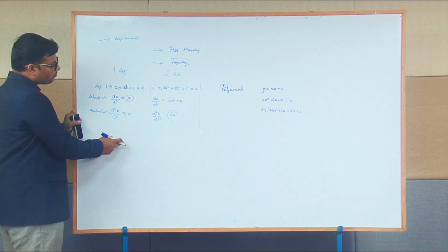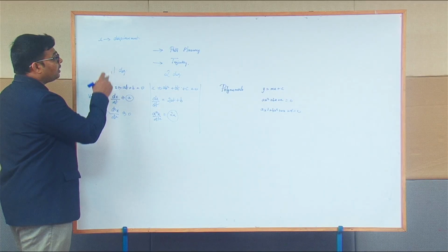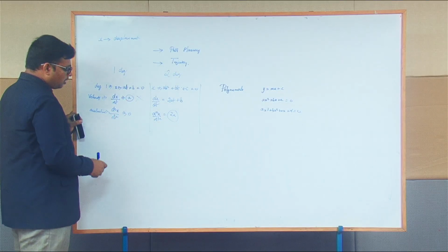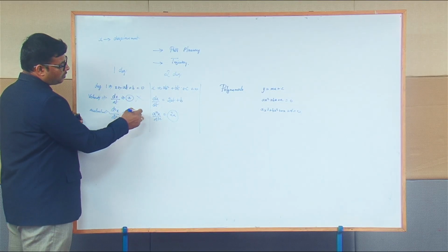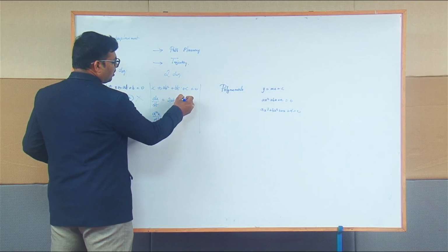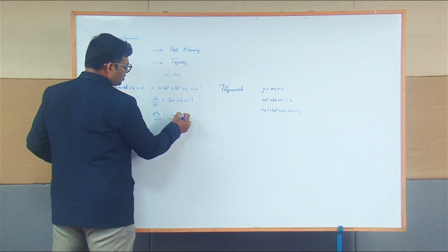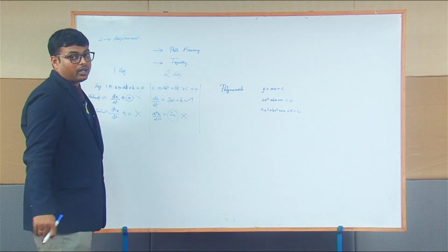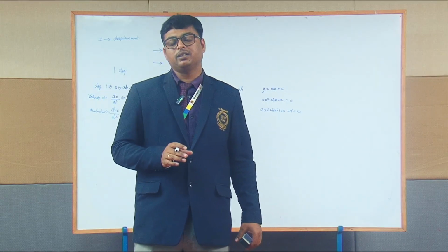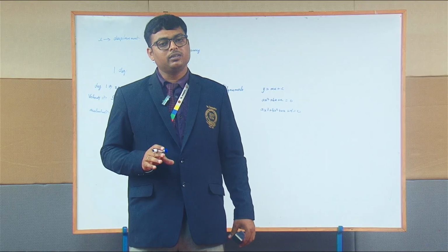So look at the first degree. If I am having a straight line and I differentiate the displacement, I get the velocity as constant, which is not permissible. And if I double differentiate that, the acceleration becomes 0, which is also not permissible. If I go for a 2-degree polynomial, I will have velocity pertaining with respect to time, whereas acceleration becomes constant, which is not permissible. And that is why we require a cubic polynomial for representing a path. A path is always confined to a cubic polynomial, which is of degree 3.